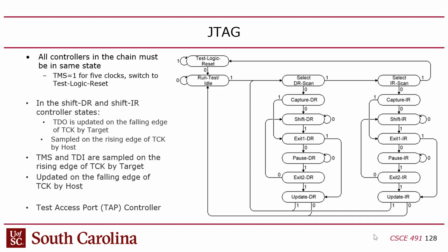So if you guys were wondering, like when you took 313, why does it take so long to program the FPGA? I mean, I get USB is slow, but still, like, megabits, right? And you look at the program file, the sof file that you guys generate, it's only about a few megabytes, right? So it should only take a few seconds to program the FPGA, but it could take a while. And the reason is because it's one bit at a time, right? And you have to put it into the right mode, so there's some overhead. So basically it takes 8 times longer than you would expect it to take.